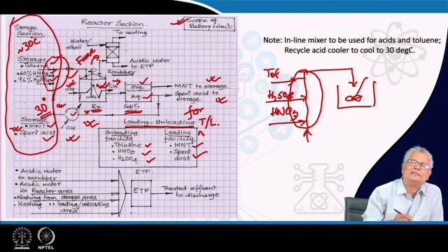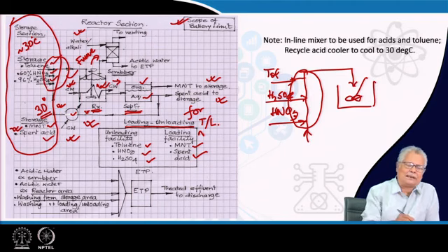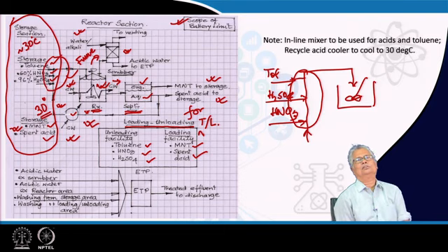So, this fume has to be scrubbed and the NO2 has to be removed from there. The scrubbing can be done with plain water, or it could be done with a little bit of alkali. It could be caustic soda, it could even be a light dilute lime solution. But if you are going to use lime solution, there is a chance that there may be clogging in the packing that you may use in your scrubber. So, possibly what you will be preferring in this particular case is a very dilute solution of caustic.